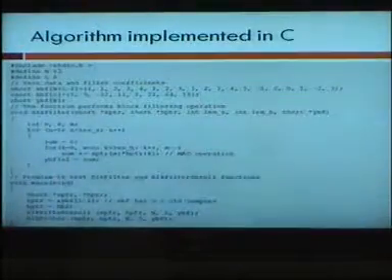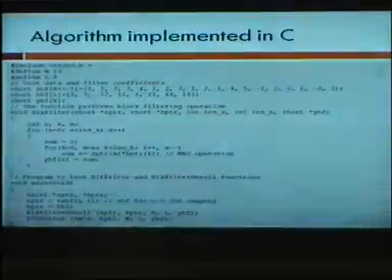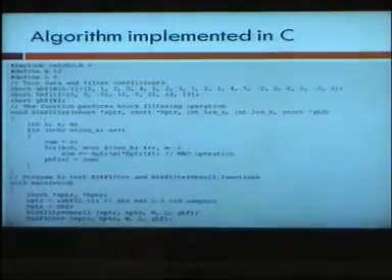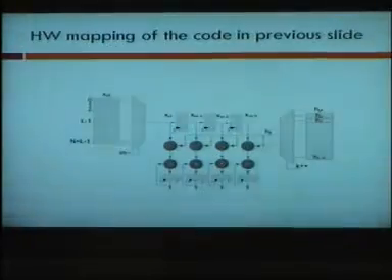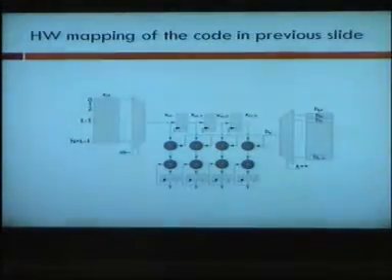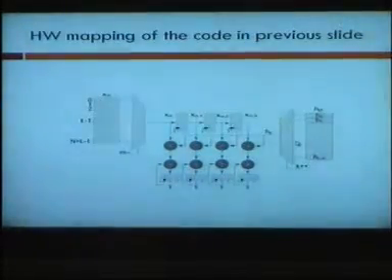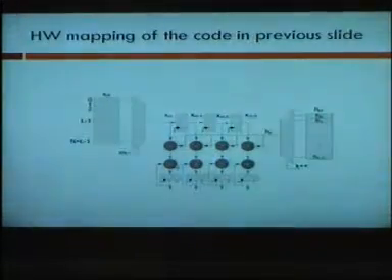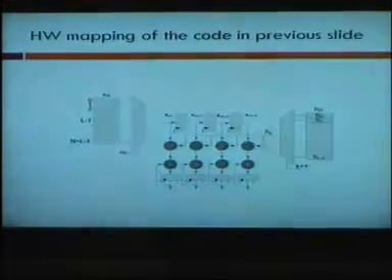So once we say my requirements are such that I want to do this in a single cycle or 2 cycles or 5 cycles, depending upon how much budget I have, I need to come up with architectures. Once we say architecture, the code will change into a figure like this. Architecture means you have this X buffer which you had in software as well, and you have this H buffer which you also had in software. These are the buffers, and obviously you need to access them, like you do with pointers, and you get X, you get H, you multiply.